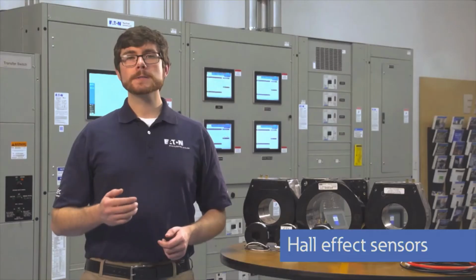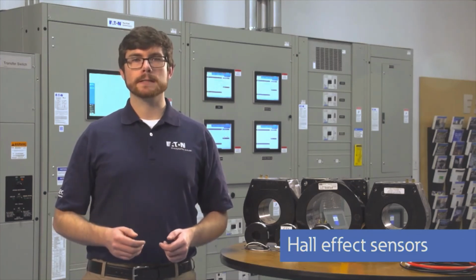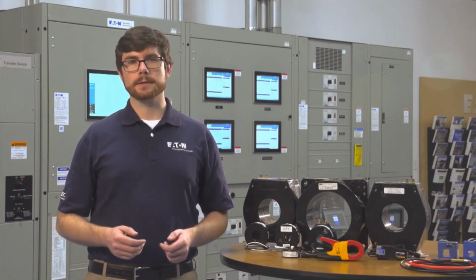However, as the current that is being measured increases, implementing this method requires the use of large, high current rated, and low ohmic value resistors that requires making a break in the circuit and adds an additional electrical component to the system. Just as shunt resistors can measure both AC and DC current, Hall effect sensors can also measure AC or DC current.